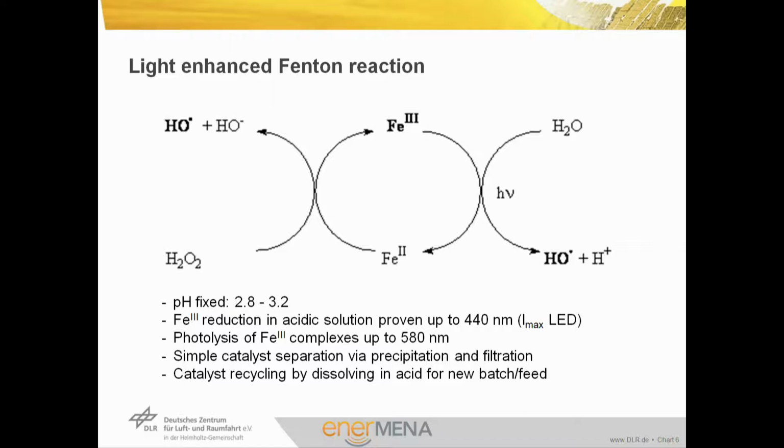There is also another benefit. The catalyst can be separated much more easily from your treated water than the titanium dioxide, as the filtration is not as critical, and the recycling of the catalyst is very simple, as it can be dissolved in acid and then it can be produced newly for the same reaction as before. With the titanium dioxide, sometimes there is a poisoning of the catalyst by contaminants like chlorine or like some heavy metals that reduce the catalytic activity.